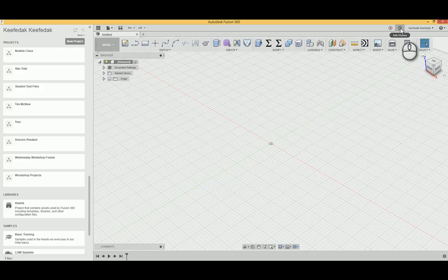And you'll find that sometimes if it's a really large file, it will just drag. So you can actually speed things up quite a bit by going offline and doing your work. It'll save it locally, but then when you're done, you save it, go back online, and let it go back up to the cloud. That's just a little trick that will speed things up. We don't have to worry about that with what we're doing today. It's just for when you have a large project. So I'm going to go back online here.